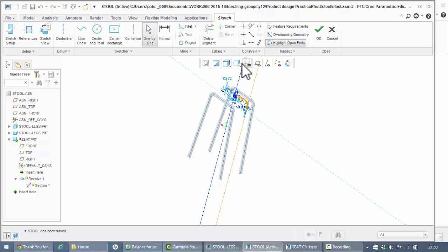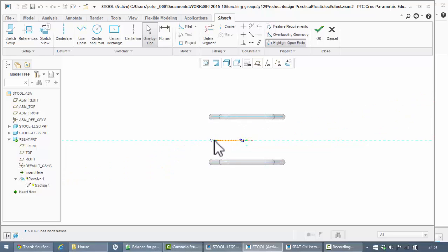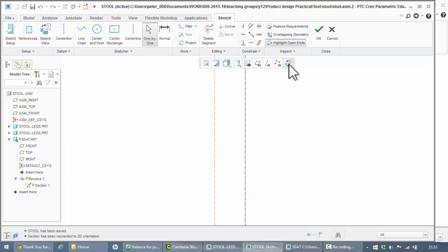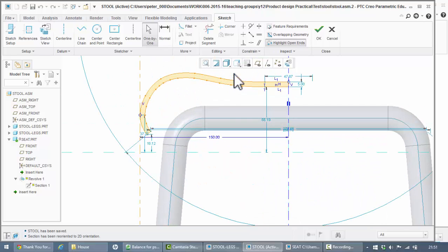If we look at it from the top, maybe that might show it better. Yeah, we're stopping here, so when we swing round, we're clipping that. So if we look flat onto the sketch and zoom ourselves back in, I'm going to just change this measurement to 200.